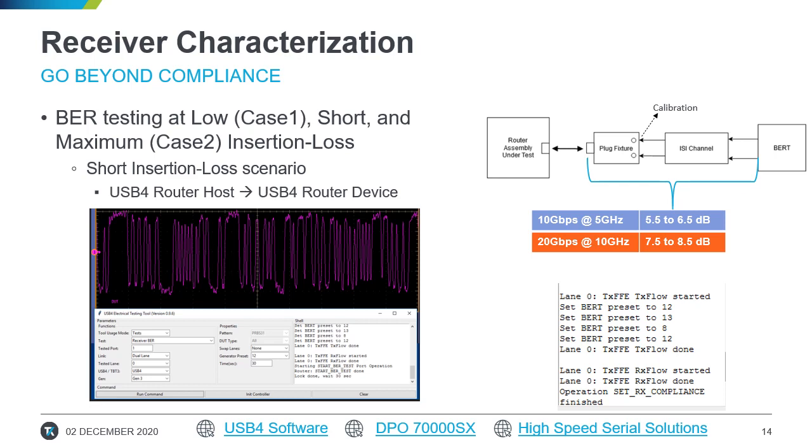But let's consider again a scenario where we have a device under test, and then we have a flash drive. That's a real-time scenario, and both don't have any retimers or redrivers in it. So how can we mimic that? That's something we had in USB 3.1 or 3.2. We used to call it the short channel test.